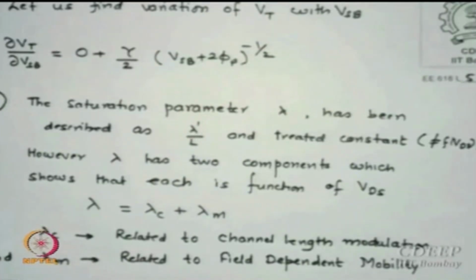And since mu varies with the electric field, we are now applying larger voltages, larger fields, because channel length is reducing and voltage is not scaling down. So we have fields which are not small enough now. For long channels, this issue was not very strong. Why? With channel lengths of 1 micron, 5 micron, 3 micron, even 0.8 microns, the supply was 3 volt, 3.3 volt. Now voltage is only 1.2 volt or 1.5 volt, and the channel length has gone to 65 nanometers, 45 nanometers. You can see how much the fields are suddenly boosted up now.